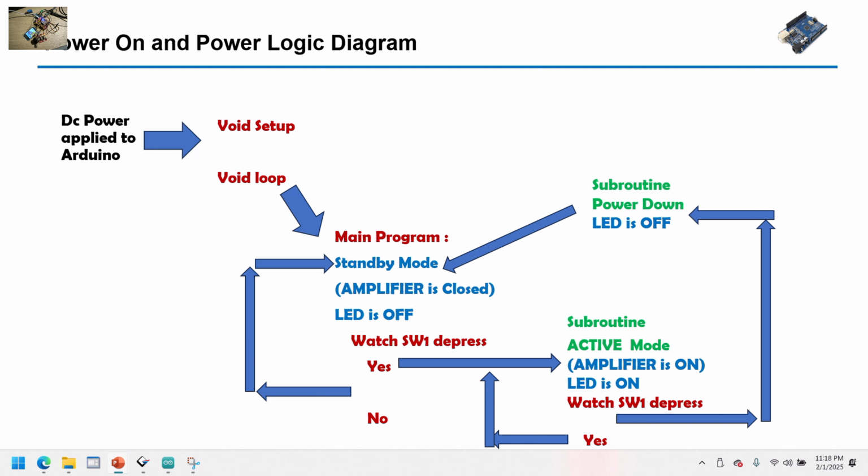And then it watches SW1 for a press. Currently no one has pressed it, and the program keeps running here. It asks if SW1 is pressed; if no, it keeps running. And if the user presses SW1, the answer is yes, and it goes to the active mode subroutine. The amplifier is on, like when I press it here, and the LED is on, and now it is watching SW1.